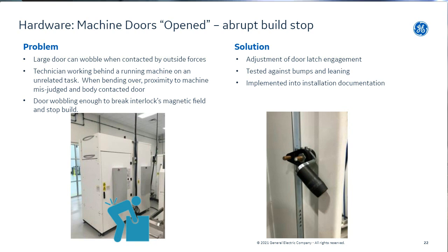It starts beeping, he freaks out, everything's fine, it wasn't an important build, but real quickly, we just opened up the back door. These latches have some tension adjustment on them. It's much more snug now, and it's become part of our installation qualification checklist: let's make sure all the doors, if you bump into them, cannot trigger the interlocks.